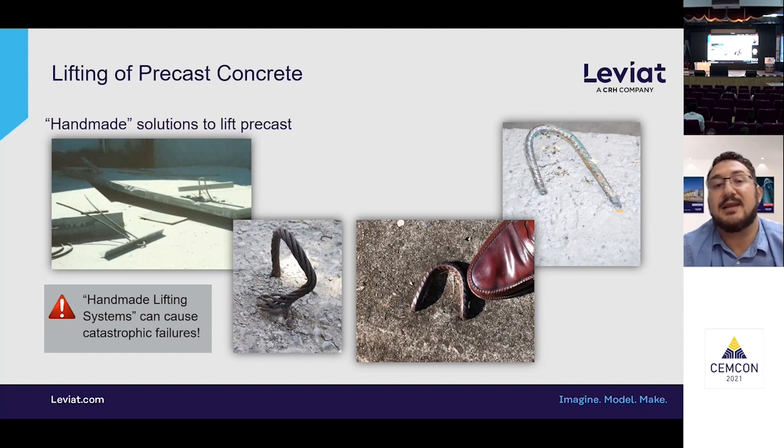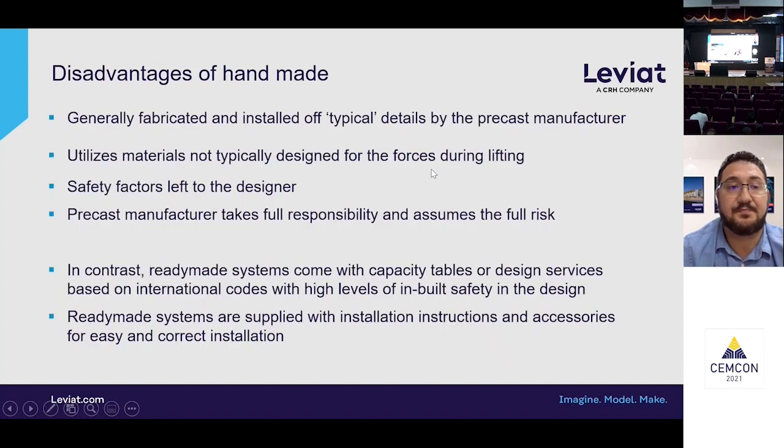They can lead to catastrophic failures because the materials themselves are generally not designed properly or taking into consideration the full safety factors or the full forces that are actually present during the lifting stage. So the disadvantages of handmade solutions: they're generally fabricated and installed from typical details by the precast manufacturer.